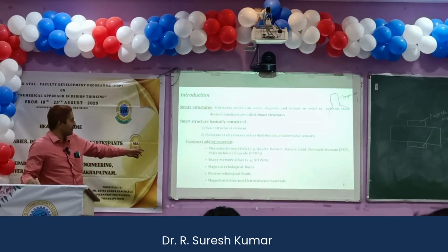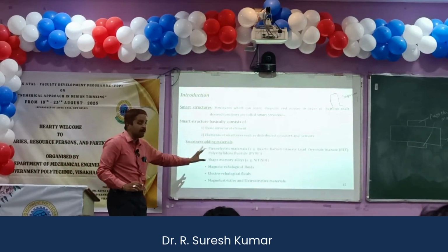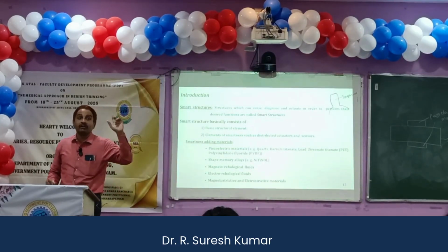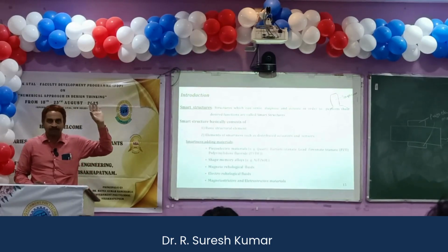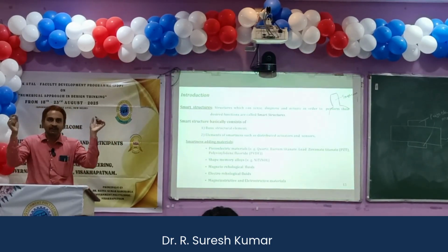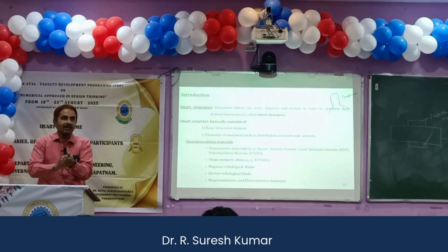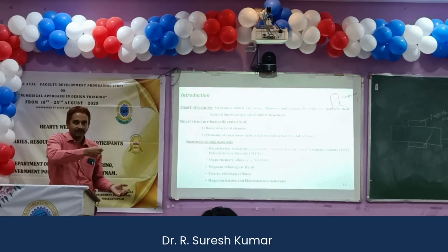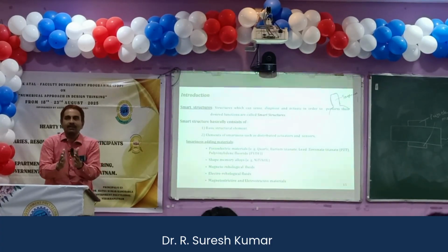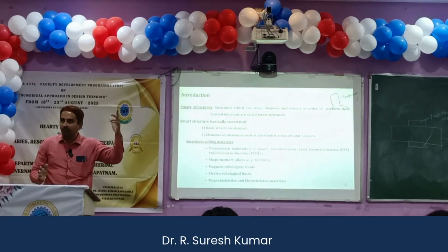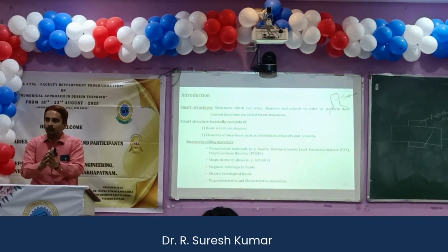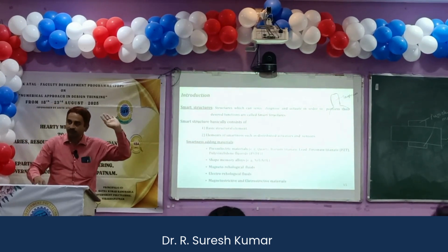So that is shape memory. The material or structure will remember its original shape. After that, you compress it and apply heat to it. If you apply heat, it will remember its original shape and come back to the shape which it had.